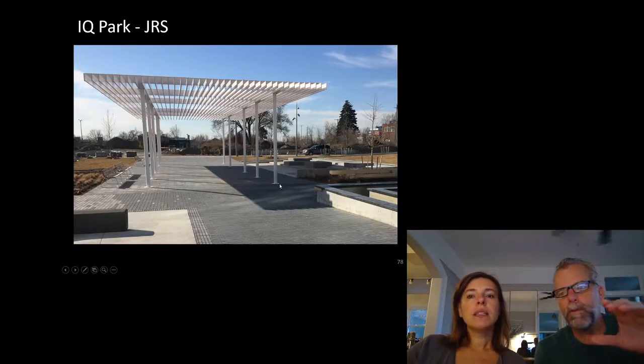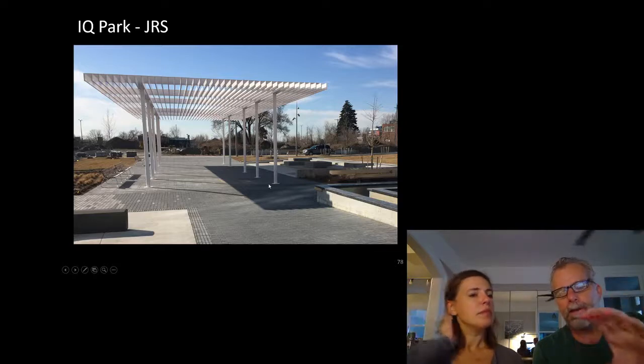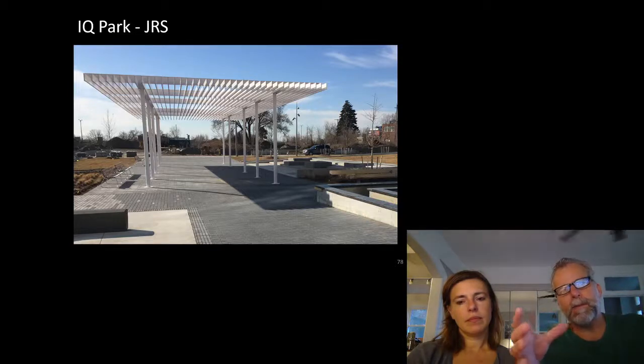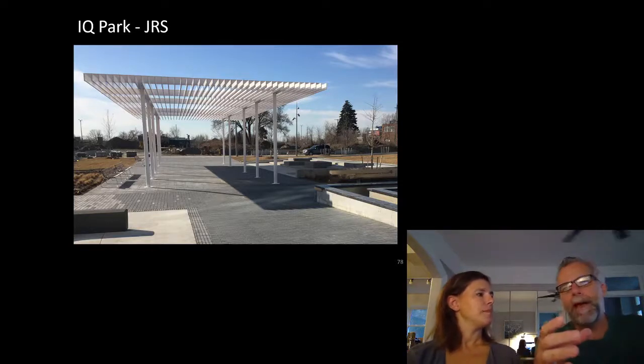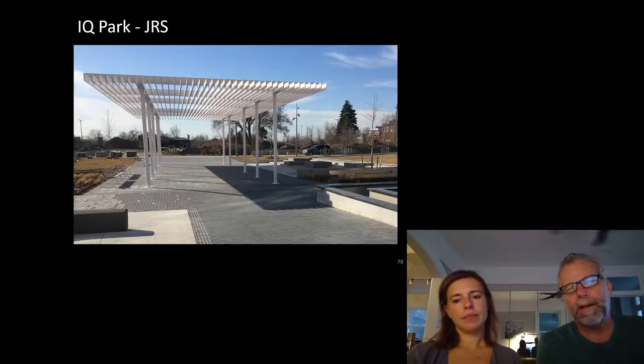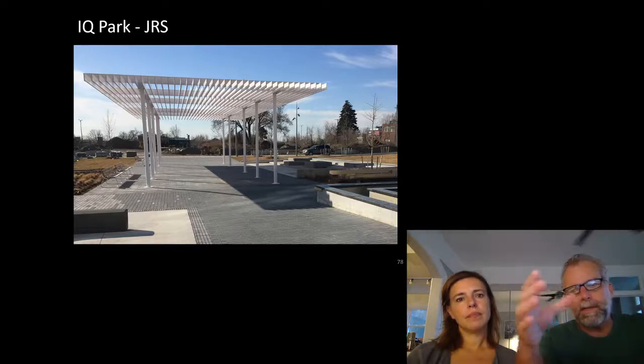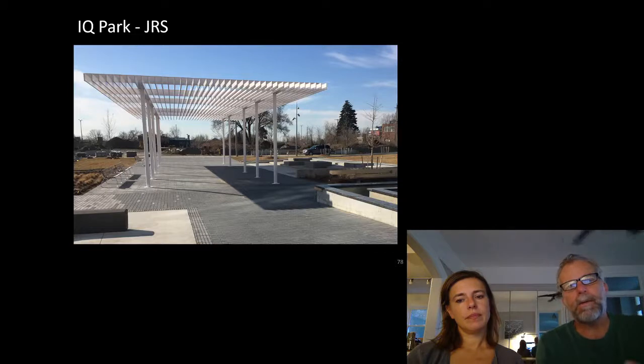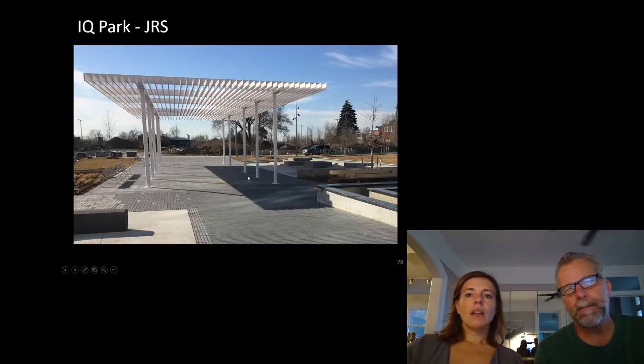What we would normally see at column bases is a pier that sticks up roughly 200 millimeters, bigger than your base plate. Your base plate would be roughly 150 millimeters smaller, and then your column 150 millimeters smaller than that. So the normal condition is quite a large concrete pier with exposed anchor bolts, but you've managed to get something really elegant and minimal. That's a cover plate. The real connection is happening down below grade.